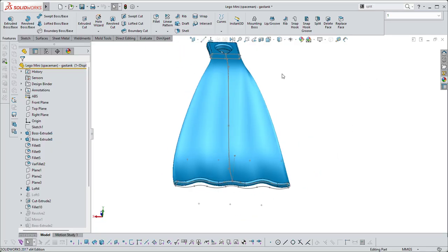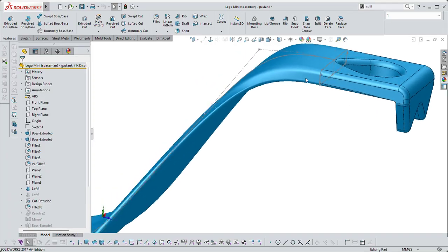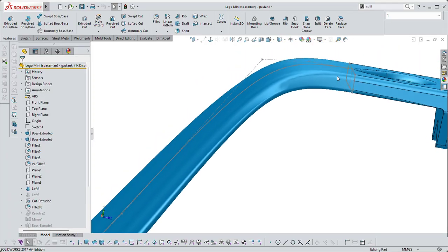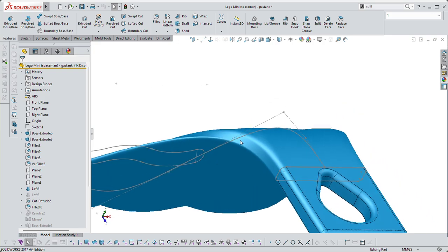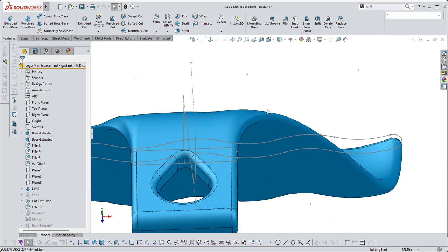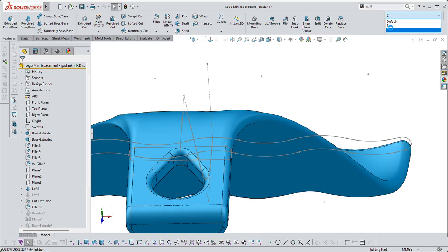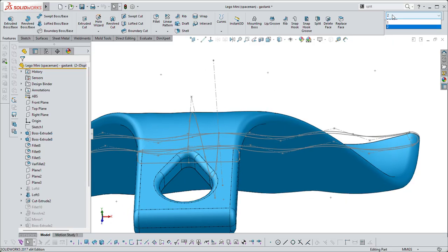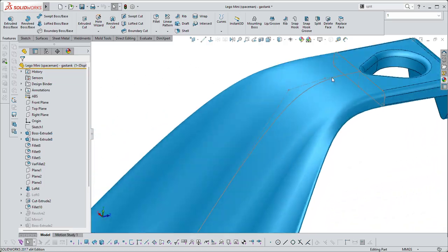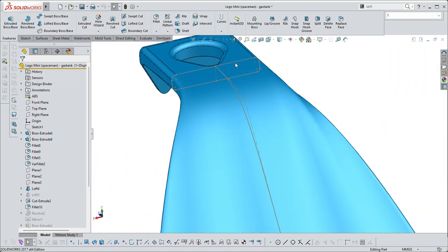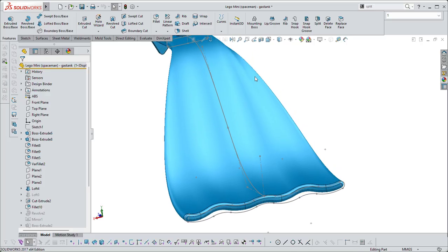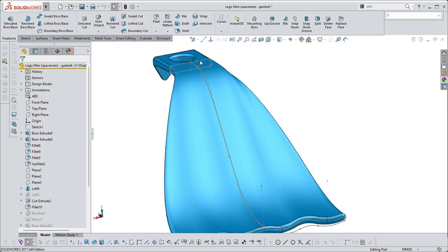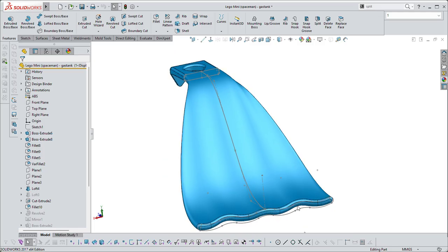But this first one doesn't really model as smoothly as the second one. You can see that face there, that little bit there, I can't grab just a bit. It does something weird on the one side, which it doesn't do on the other, which, if I have a look at the other one, is much better. That has to do with how many segments I have in the sketch. So I've only got 7 in this sketch at the top, and at the bottom I've got about 12 or 13. So if I really wanted to fix it up, I just need to break that sketch up into more or to combine these ones.